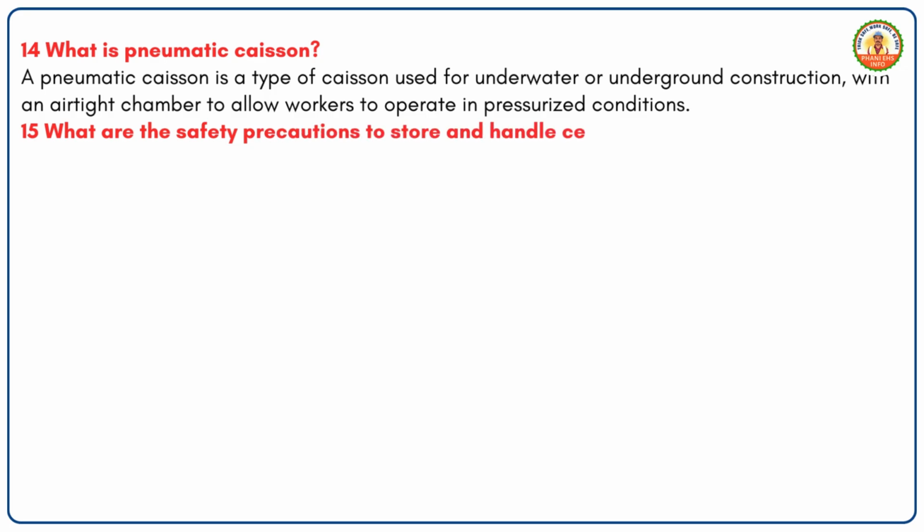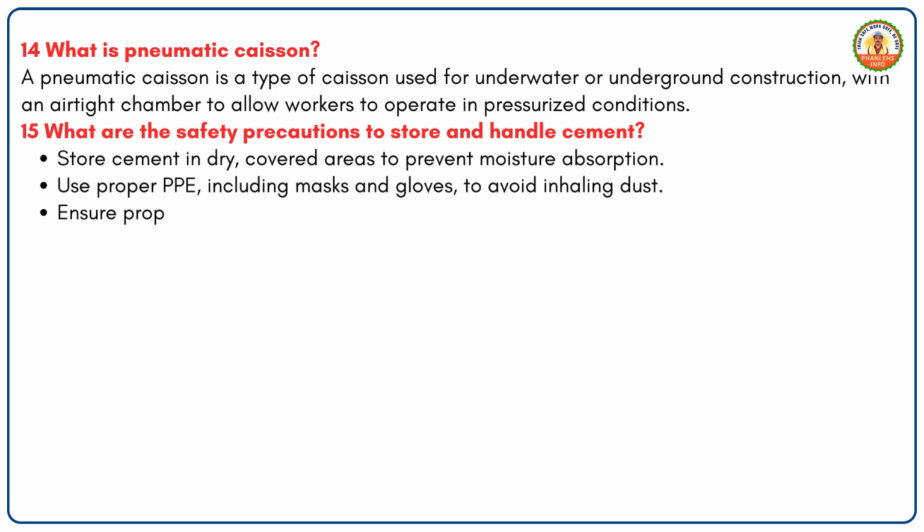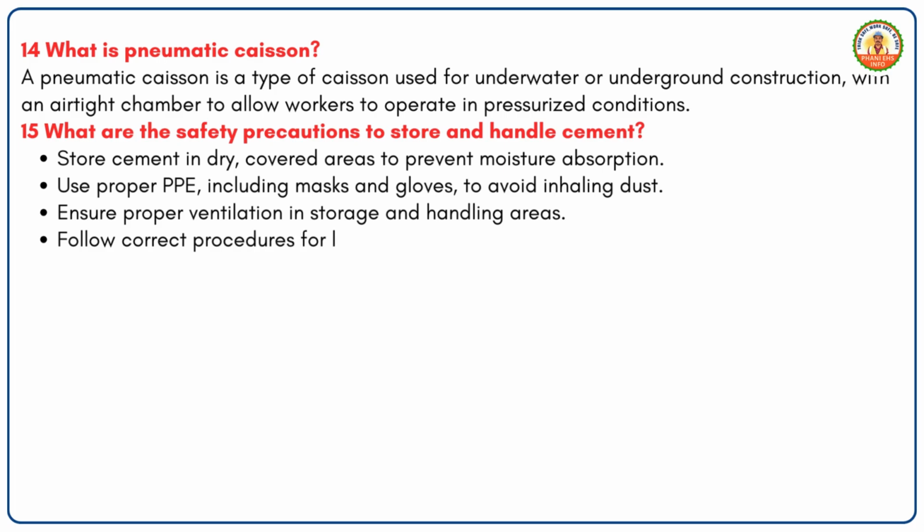Store cement in dry, covered areas to prevent moisture absorption. Use proper PPE, including masks and gloves, to avoid inhaling dust. Ensure proper ventilation in storage and handling areas. Follow correct procedures for lifting and transporting cement bags.